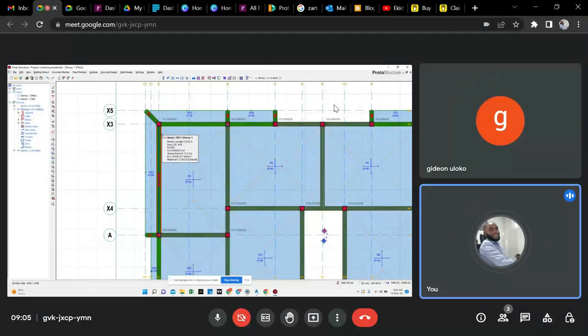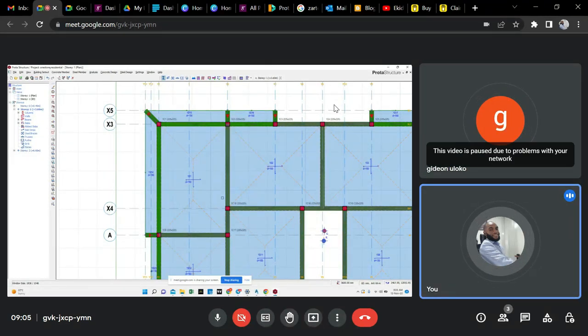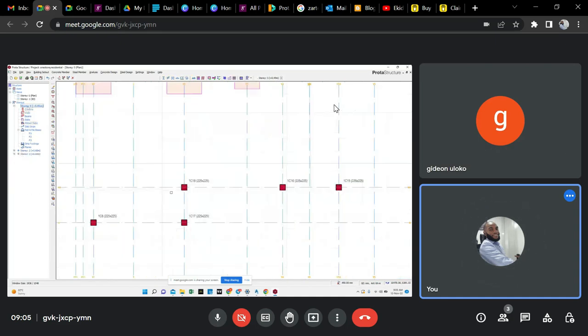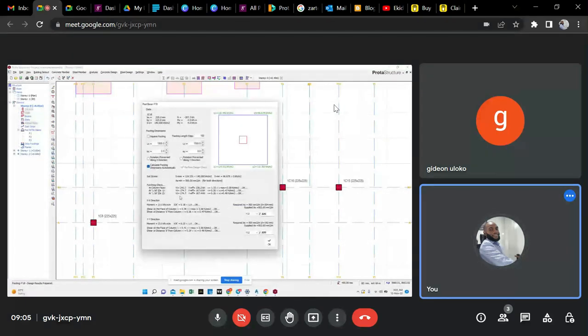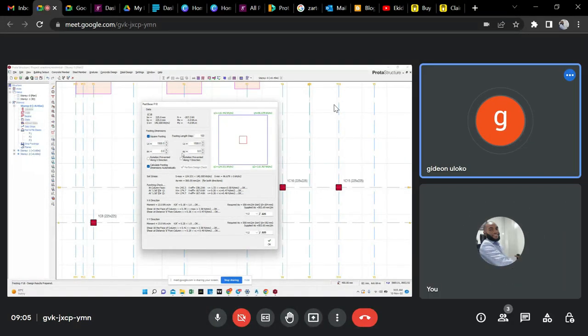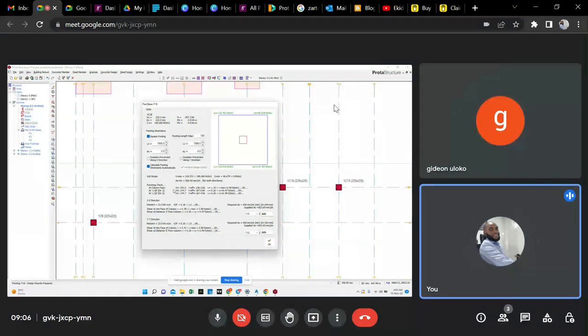So I think if you go to foundation right now, check column 18 and column 17. Check if that 250 we're going to pass it, and check column 18 and check if that footing depth will pass. I think it will pass because the building is not that big, and you can also see that the size of the footing here is 1.5. Yeah, 1.5, it has increased a bit. Okay, so just say okay first. Click on okay first, and then wait.